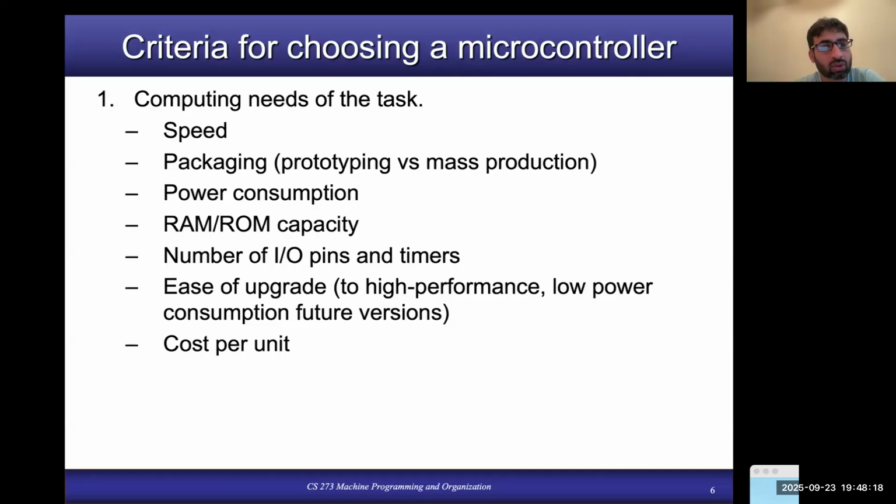And then maybe you also will need multiple timers. So again, it all depends upon what kind of application or what kind of design you are developing. Ease of upgrade to high performance, low power consumption future versions of the same microcontroller. Let's say you have analyzed all these factors like speed, packaging, power consumption, RAM, ROM capacity, and number of I/O pins, and after that you have selected a microcontroller.